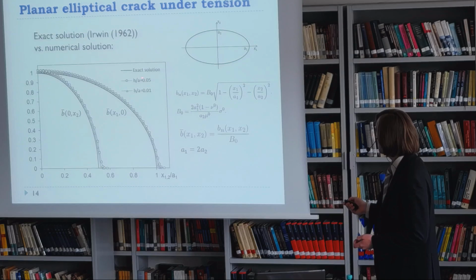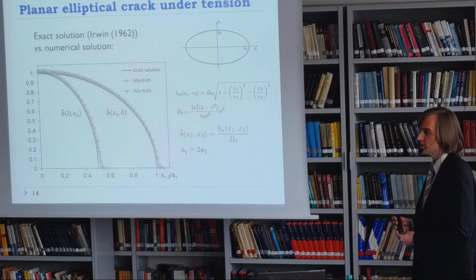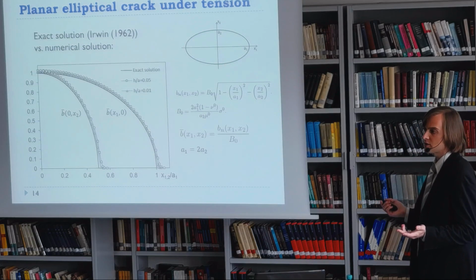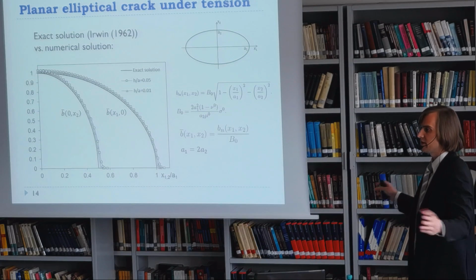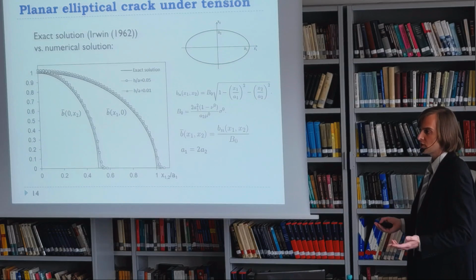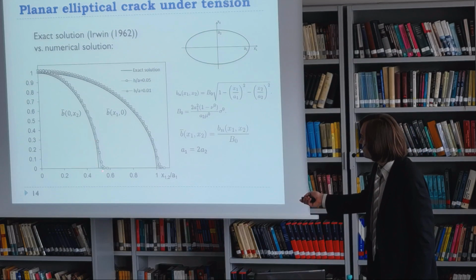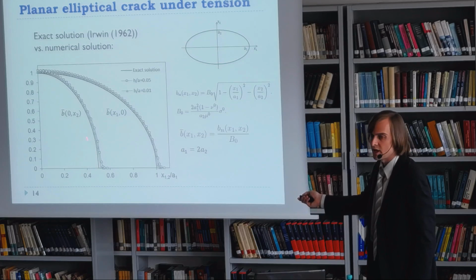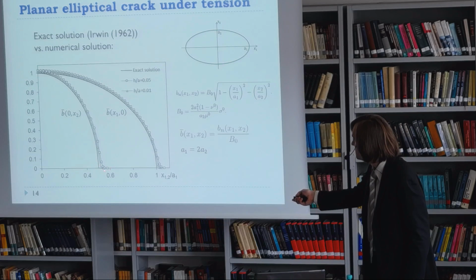These are results for different node steps. But here you may see some problem, some irregularity in the solution. As I have mentioned previously, we calculate the Gaussian approximation in the whole crack plane. So it means that our weight function has infinite support. And what happens as a result is that our solution wouldn't tend to 0 at the crack edge, because we're calculating it in the entire plane. So as you may see, it tends to 0, but not where it should be.